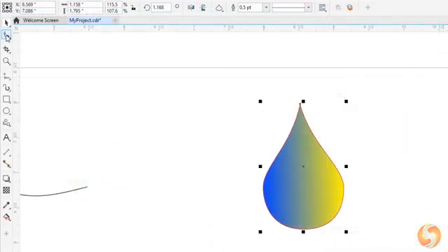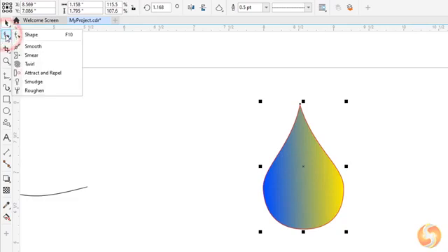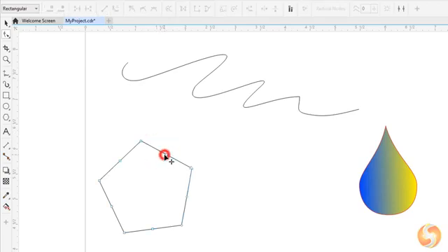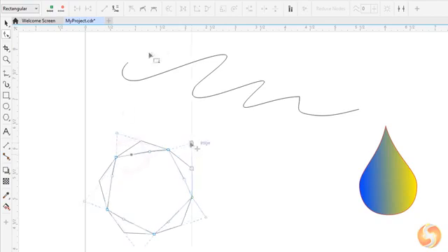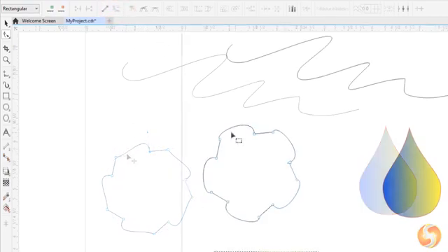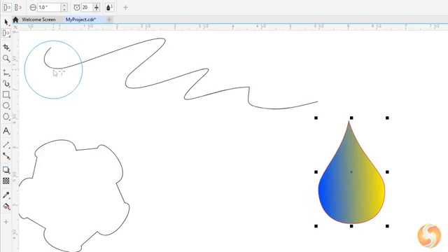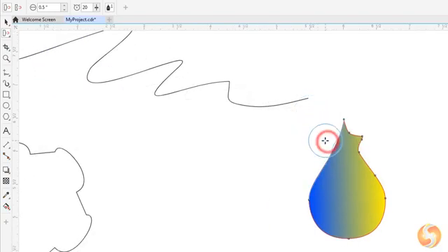Whereas, to edit the vector shape, you can use all the tools collected inside the second button of the toolbar. With the Shape tool, you can move nodes and tangents to refine the vector shape and double-click on it to add new nodes if necessary. Enable the other tools to apply nice effects by clicking and dragging over the vector paths.